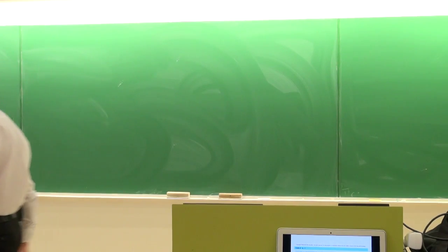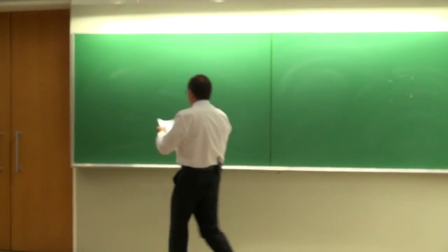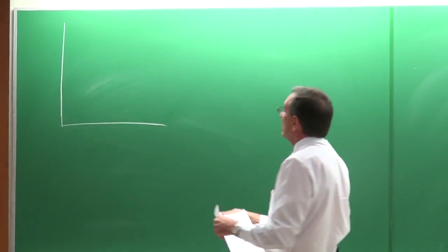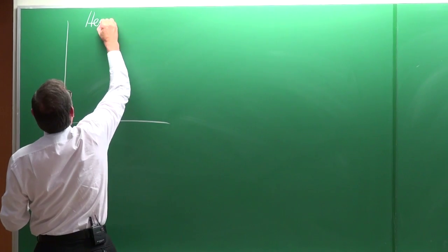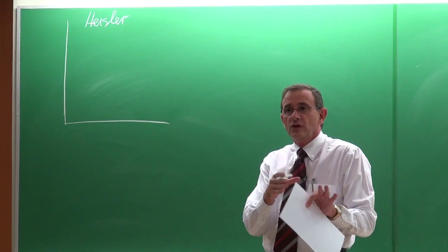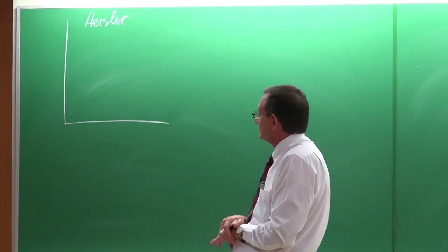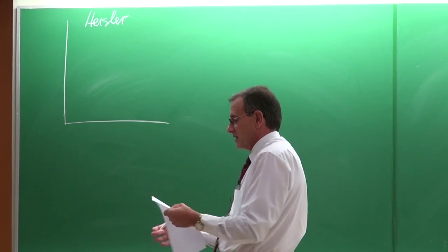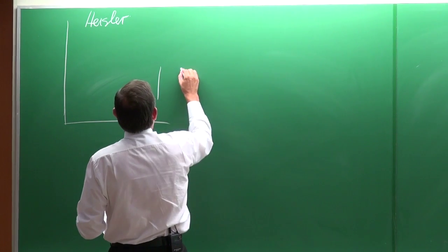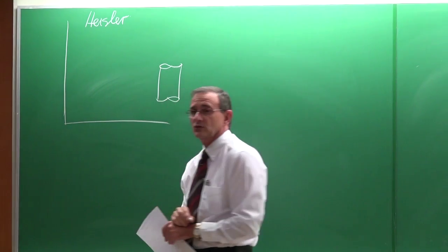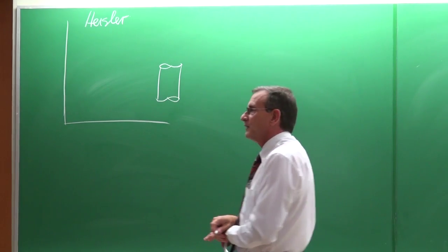So if you go and look at those charts, then you will see typically, and there are 3 sets of charts in your textbook. They're called Heisler charts. And there's one for a plane wall, there's one for a cylinder, and there's one for a sphere. And on all of them, they are actually very user-friendly in terms of the use. So for example, for the cylinder, they will give you a sketch like that. Okay? So that is the second graph in your textbook.